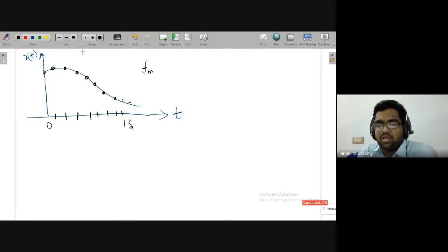So that's why they give one formula to avoid distortion at the receiver side. What is our aim? We represent the analog signal in terms of digital data, and from the digital data we have to recover our original analog signal. That is the aim. So when taking samples, the sampling rate must be at least greater than 2 Fm. Fs must be at least greater than 2 Fm.